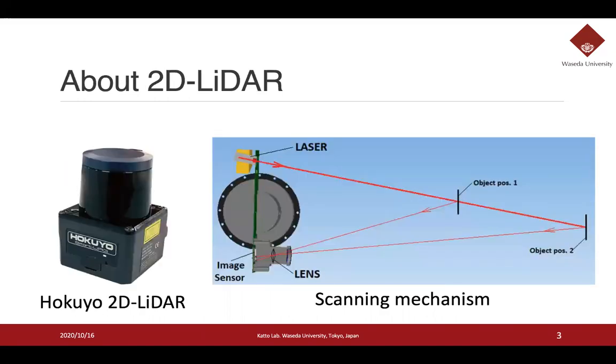Before I introduce how to detect curves from sensor, I'd like to explain about 2DLiDAR. 2DLiDAR is the distance measurement sensor, also known as 2D laser scanner or 2D laser range sensor. The picture to the right is the top view of the 2DLiDAR and shows scanning mechanism. 2DLiDAR measures the distance to an object by illuminating the target with laser. The difference between 2DLiDAR and 3DLiDAR is the number of scanning lines. This means, in other words, 2DLiDAR senses using only a single horizontal scanning line. In many cases, 2DLiDAR is used for performing detection and ranging tasks.